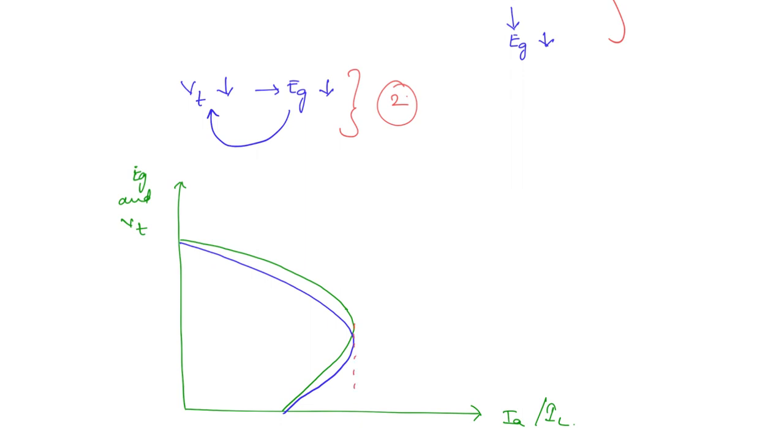This current here you can take as Ia max, and also this is the drop due to Ia Ra, okay? This is the internal characteristic, that means the variation of Eg with respect to armature current, and this is the external characteristic.